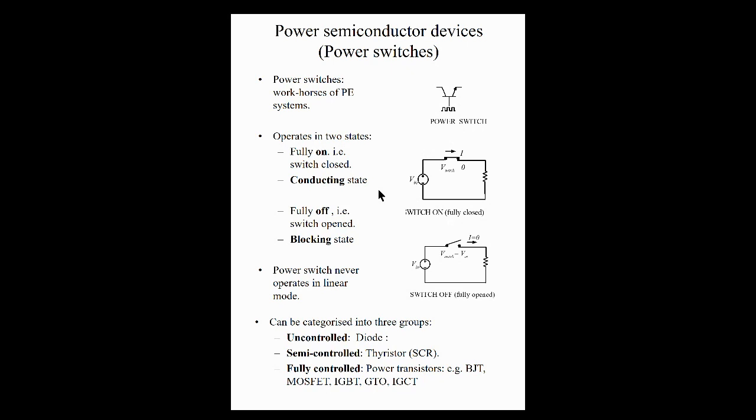Right, so with the ideal switches, we will have no losses, but in reality, we're going to have losses, and the losses are normally when we have our transition between on and off, right? Because it's not an instantaneous process going from on to off or off to on. All right, so the important point to note is that these switches, they're not linear.